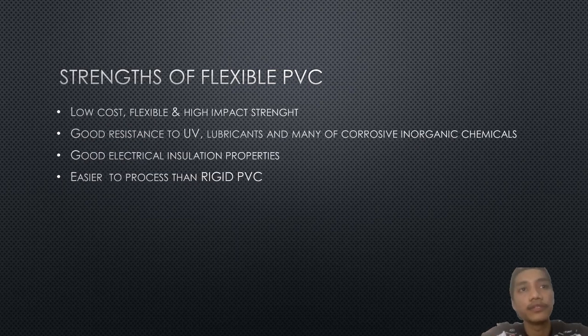Strengths of flexible PVC, which is about the advantages of flexible PVC. First, low cost, flexible and high impact strength. Next, good resistance to UV, lubricants and many corrosive inorganic chemicals. Third, good electrical insulation properties. And lastly, easier to process than rigid PVC.